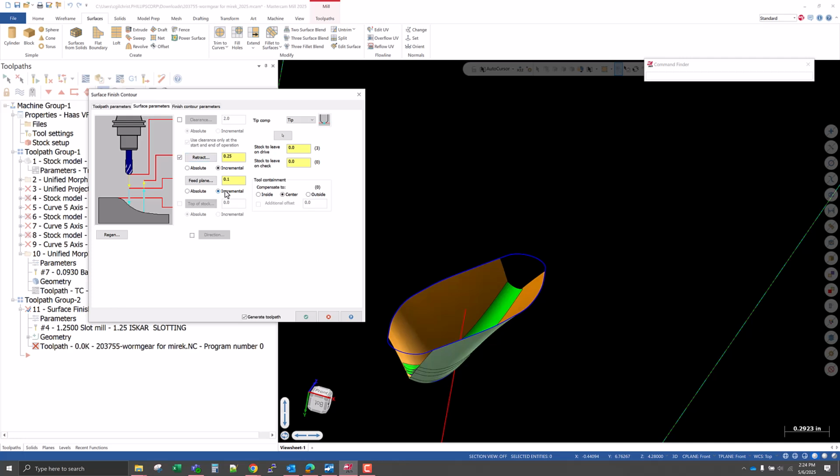This is not incremental like we're going from absolute to, from G90 to G91. And I'll set a clearance plane at 2 inches incremental because I want a point that's going to start above the path. It's going to wrap it down to where we're actually starting the feeding from, and then it's going to go and start cutting the part.